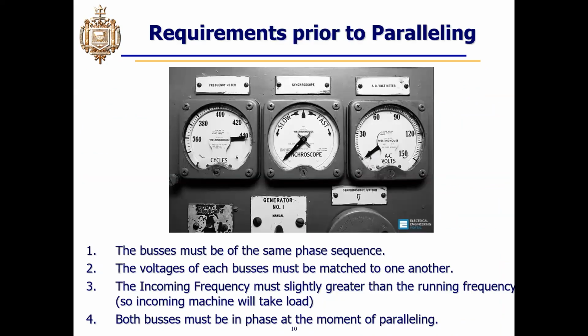So with alternating current, a lot of your power supplies, you've got to be able to transfer power from one source to another. So if you want to shut down your ship service turbine generator, for instance, and it is up and running, supplying AC to your electric plant, well, you've got to transfer the load from the ship service turbine generator to the new source. So if you're bringing the diesel online, or if you're bringing shore power online, you're going to have to parallel your generator with this new source and transfer this load.